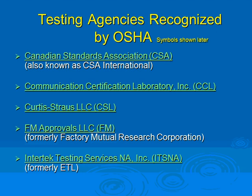When we install it, a lot of building owners want to be environmentally friendly, so they want biodegradable transformers. To get you a biodegradable transformer listing, we used to put the FM, Factory Mutual label on it. That's an environmentally friendly transformer, which is basically biodegradable, almost olive oil that you can put in that transformer. So that's how I dealt with that one.